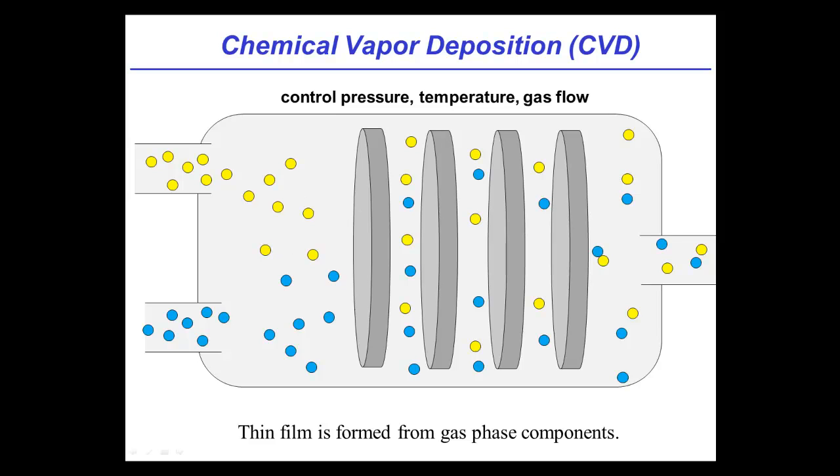How many wafers can you do at a time in one of these tubes? Well, it depends on the tube. It turns out in some modern tube systems, you'll see as many as 200 wafers. Wow. But there is a trade-off. We've actually drawn a fairly realistic picture here. You see how it looks like there's more reactant species in the front than there are at the rear. Sure. That's actually true. That really does happen, especially if you do it like this, where you inject from one side and exhaust from the other. You're just eating up all the stuff. By the time you get to the end, the last few wafers probably wouldn't look the same as the first few. Right, so you'll have non-uniformity across your system. So there tends to be limits to how many wafers you can stick in.